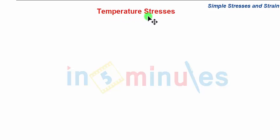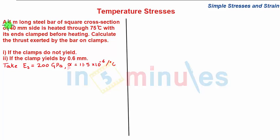We now take a problem on temperature stresses. Our problem statement is: a 4-meter long steel bar of square cross section of 40 mm side is heated through 75 degrees centigrade with its ends clamped before heating. Ends are nothing but supports. Calculate the thrust exerted by the bar on the clamps for two cases. In the first case, if the clamps or supports do not yield. Second, if the clamp yields by 0.6 mm.